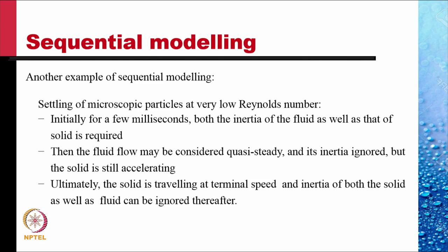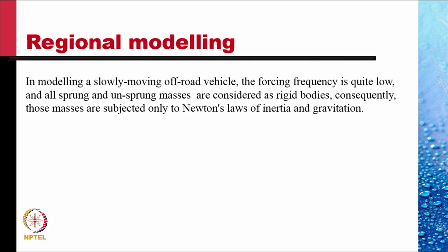Then, if the Reynolds number is very low, the fluid may be considered quasi-static after the first phase and its inertia ignored. But the solid is still accelerated. Ultimately, the solid body is traveling at the terminal speed, and the inertia, both of the solid as well as the fluid, can be ignored thereafter. We had analyzed this in quite some detail.